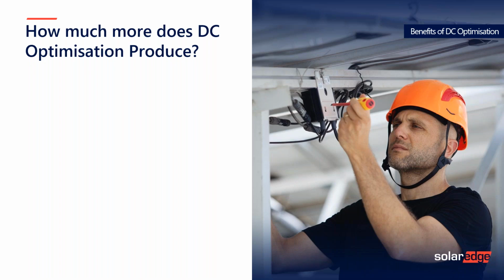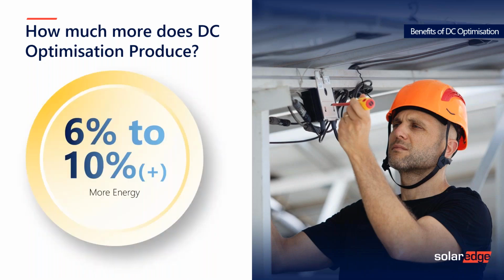all across the country, different configurations, single or dual string, and they had to be systems that a string inverter could also support. And what we did is model how a string inverter would behave in that configuration on those roofs. Through the modeling, we came out with 6 to 10% more energy than a traditional system. It was an inherently conservative analysis in that we set the voltage at a fixed point, where normal string inverters operate with variable voltages. So we fixed the efficiency, but we also set it at our 99.2% efficiency, which is generally a lot higher than traditional inverters. So we tried to make it really conservative.